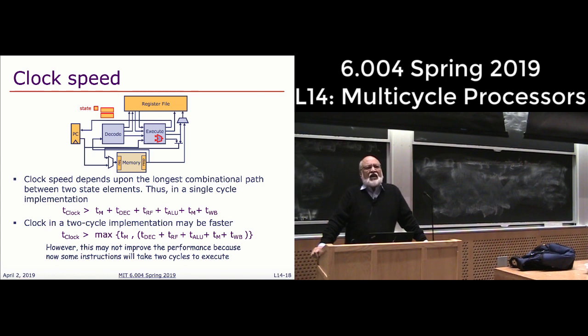Now, if you imagine that accessing memory is an expensive operation in terms of time, it has long latency, then you will discover that these two times are roughly the same. Certainly this clock is faster than the first one, because instead of 2 memory reads, it's doing only 1 memory read. That's good news. That means we can run it faster, in the physical aspects of this design.